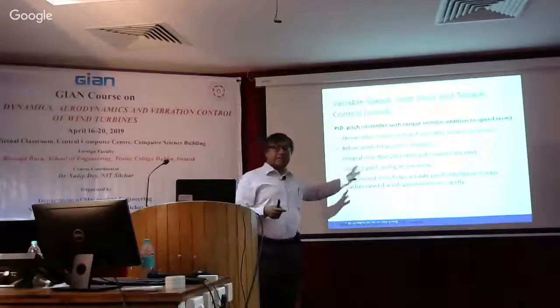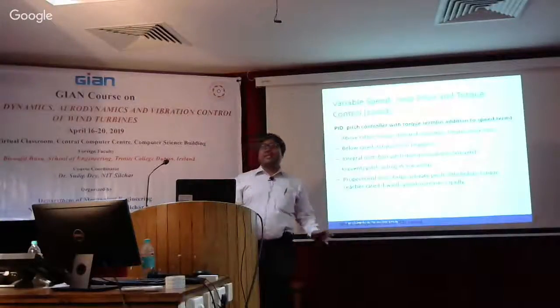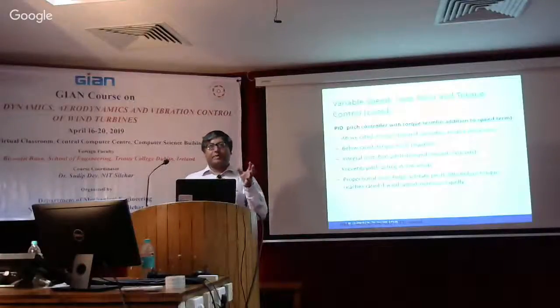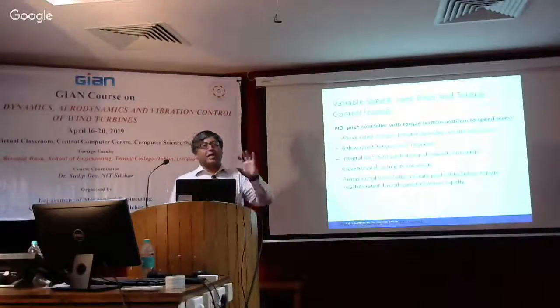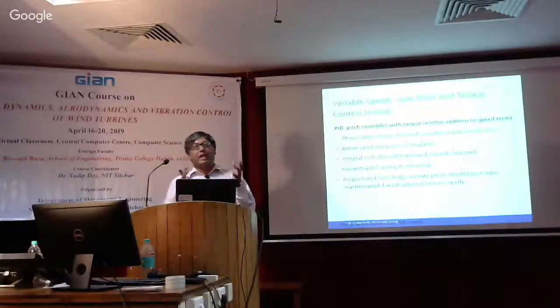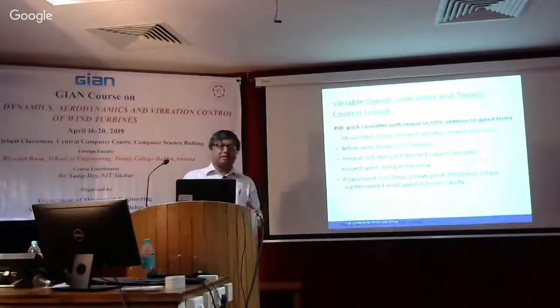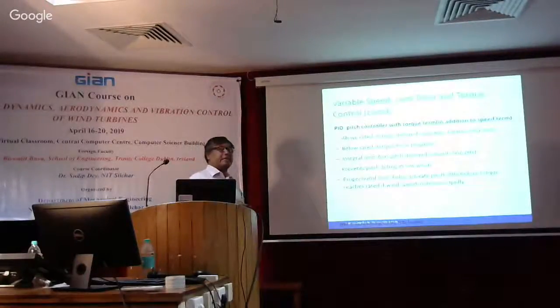In our analysis or in our discussions, we didn't actually consider the inertia of the actuator itself, because the pitch is an actuator, and so the pitch will also have its own dynamics. That system's dynamics will add to the overall system dynamics as well. So that has to be considered as well.